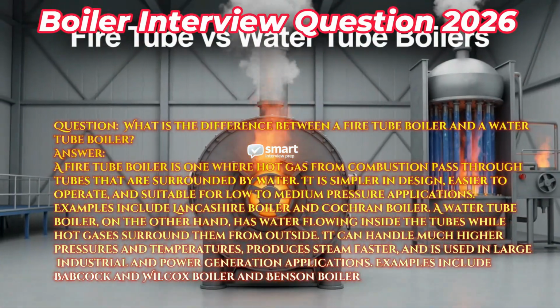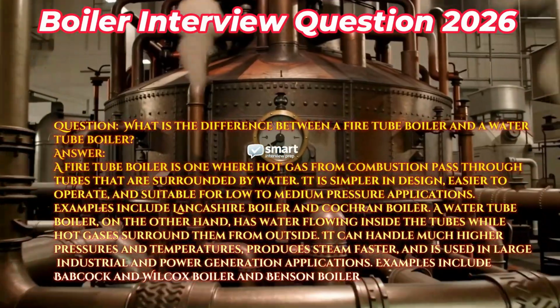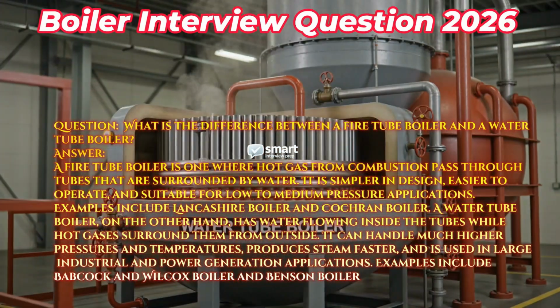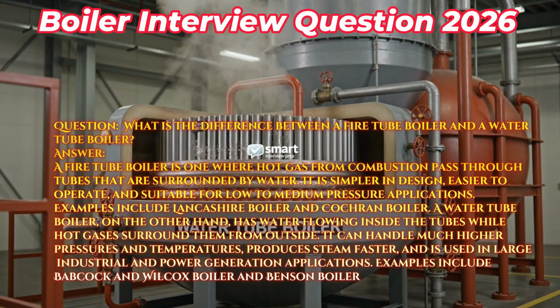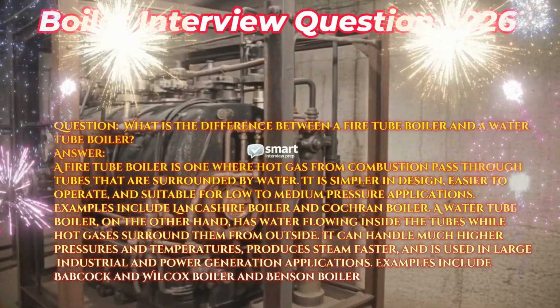Answer: a fire tube boiler is one where hot gas from combustion passes through tubes that are surrounded by water. It is simpler in design, easier to operate, and suitable for low to medium pressure applications. Examples include Lancashire boiler and Cochrane boiler.